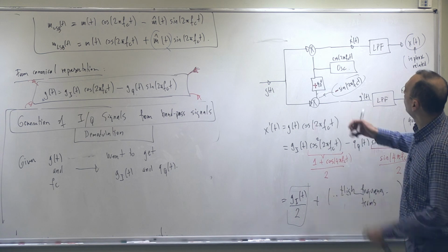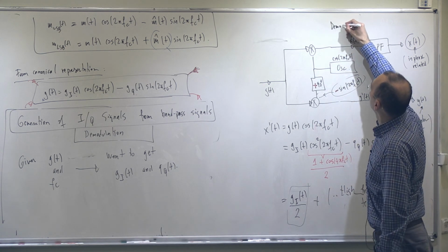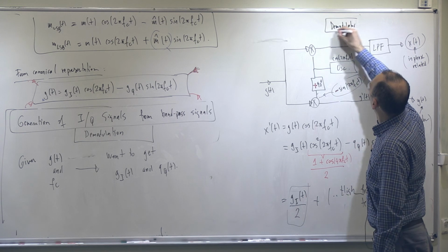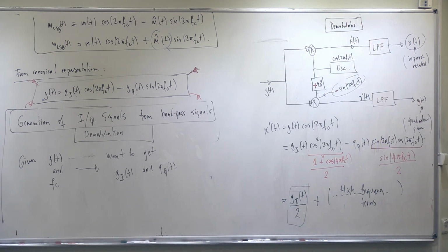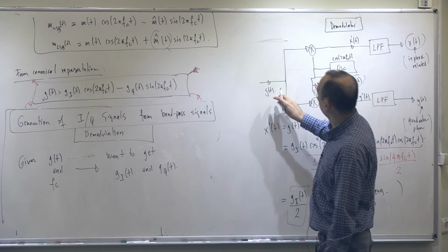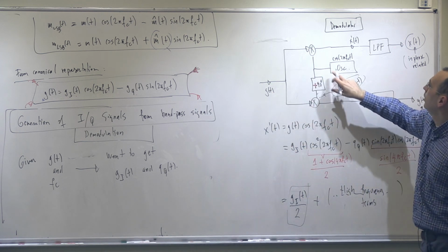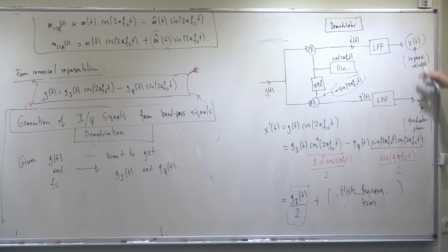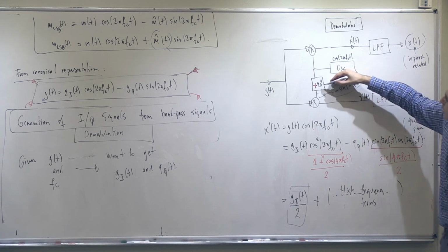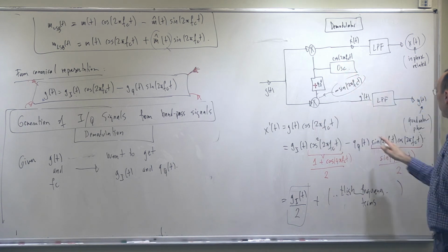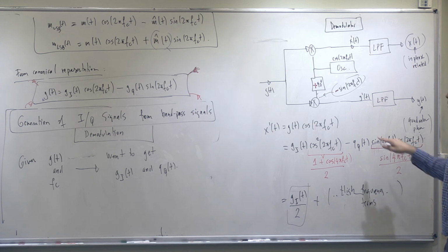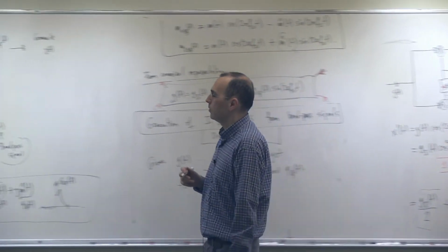Now you can see that this demodulator, this practice, works quite well. So if you have a bandpass signal, then you have an oscillator demodulating it to the IQ signals. And these are called, in hardware practice, IQ channels of this receiver. Of course, there are issues, like this should be exactly 90 degrees and so on, isn't it? Otherwise, this cancellation of double frequencies will not be happening. So you have to be very careful about that. There are some other practical details, but this is basically it.